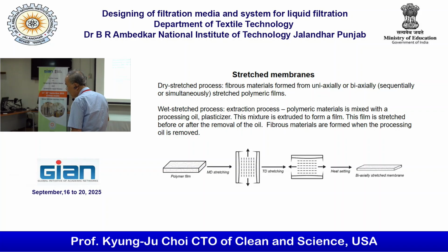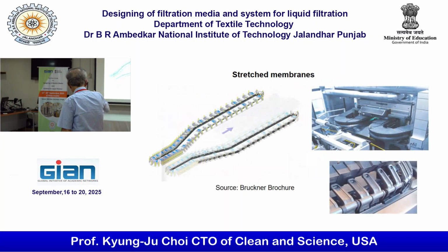So the wet stretch process is making expanded polytetrafluoroethylene film. Here it is. This is actually TDO, not MDO. MDO has a lot of roles, but this one is TDO, stretching, coming out and stretching in the transverse direction like this. See, the most important thing is this one, the clip. Clip is quite important.